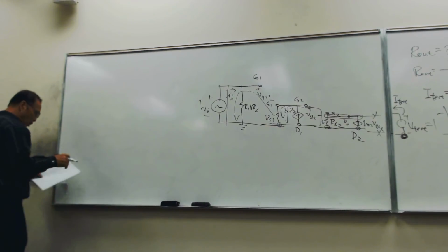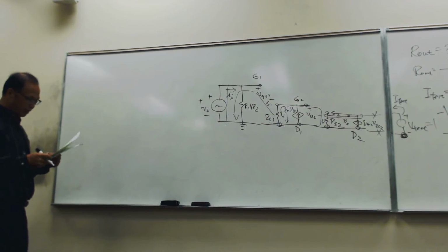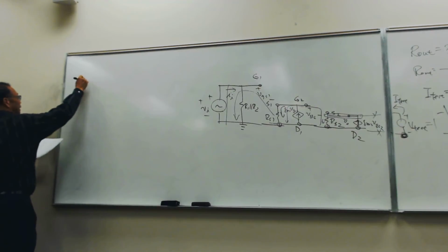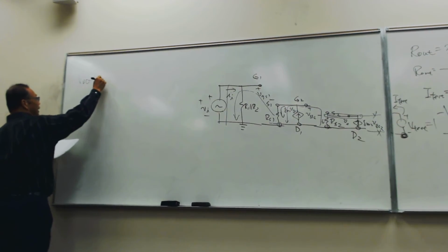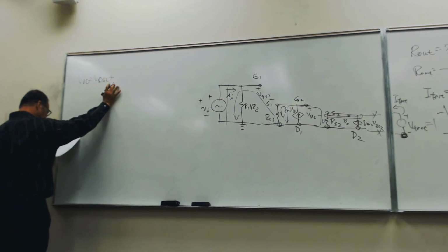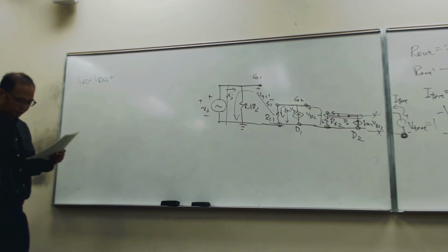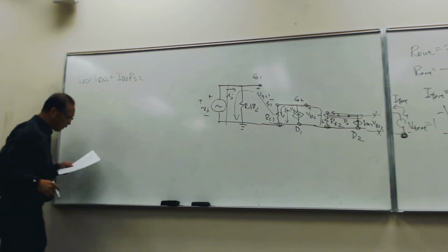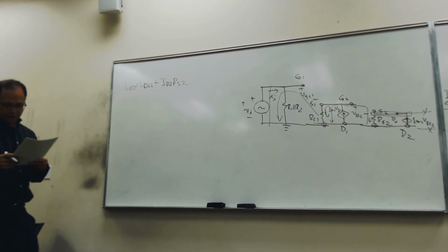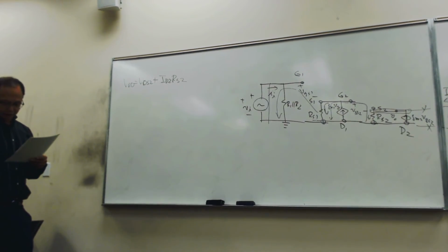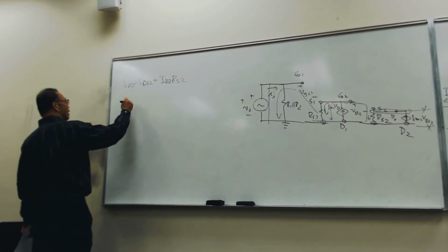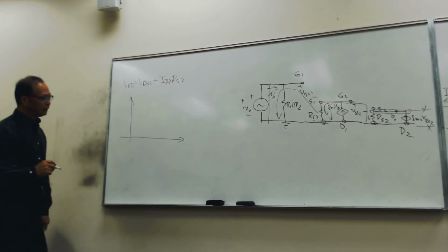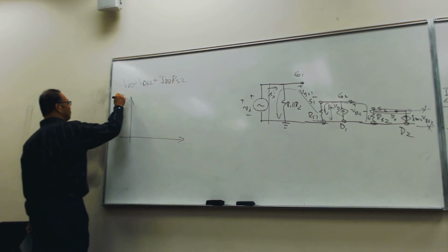Okay. So you have the circuit, right? If you look at the circuit, the output loop circuit is what? VDD equals VDS2 plus, we're talking about the second stage, right? ID2 RS2. So that's the KVL of the second stage. Based on that, you can try to figure out what are the DC load line and the AC load line.